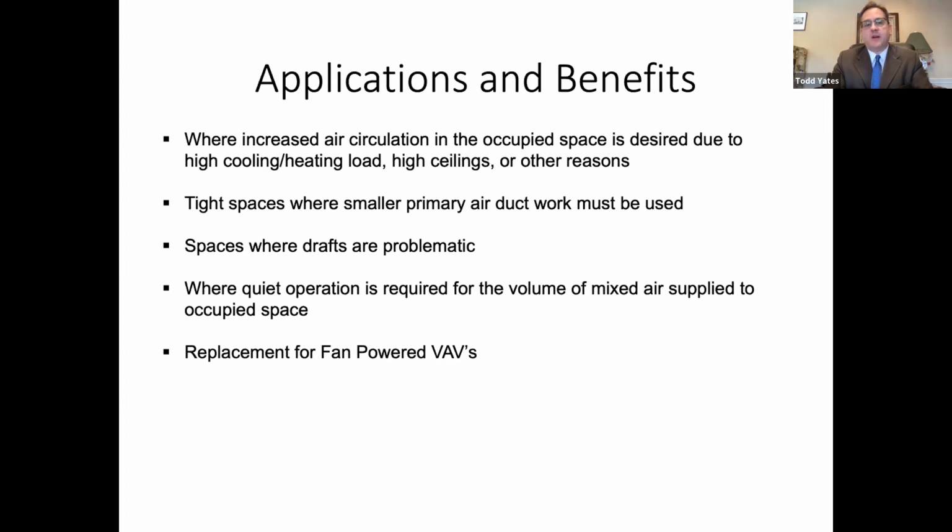Spaces where drafts are problematic is a third reason you might use these. Because it's entraining the air from the space mixing with the primary air, you still have the same cooling load that you might have, but because drafts are an issue in these areas, the air is warmer, closer to your design room temperature by the time it gets to the occupant level.